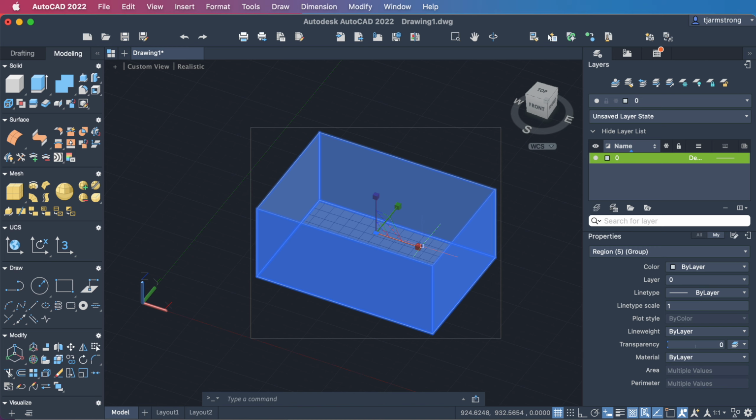You actually have to come up here. If you come up here and use this gizmo in the center, it'll change the shape, the size of the whole box. If you want to change them along individual dimensions, you can actually make this a block and specify the ability to change things on X, Y, Z axes or use the block editor.